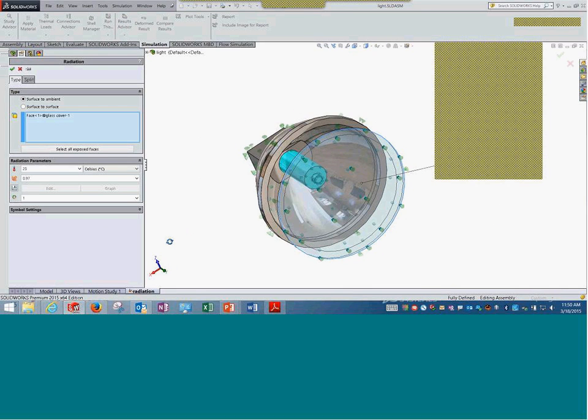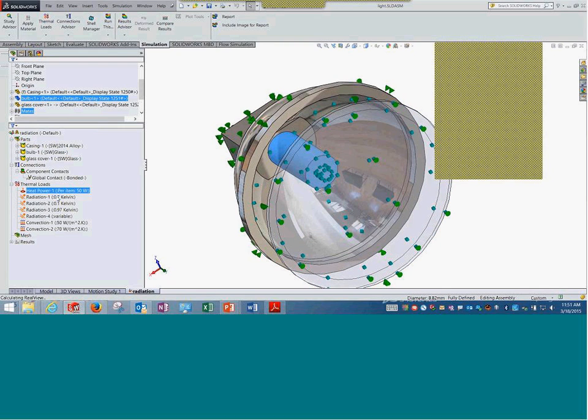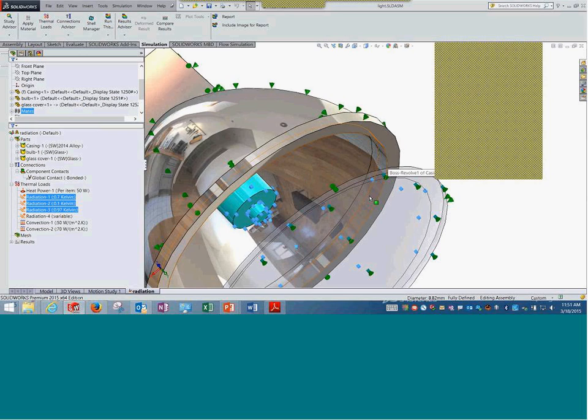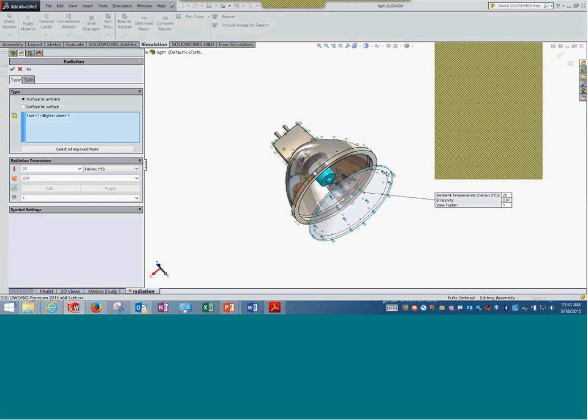Okay. So see here there are 3 things happening. This is going to create the heat, which is represented by the heat power. Then we have 3 surfaces, 1, 2, and 3, which are absorbing the heat of radiation from that part to the other part. And finally, there is one more thing called the outer surface of the gas, which is exactly in front of it. It can even emit the radiation to the atmosphere. So surface to ambient, and it is radiating from there to the atmosphere. Of course, even over there we can give the view factor, and the atmospheric temperature condition.